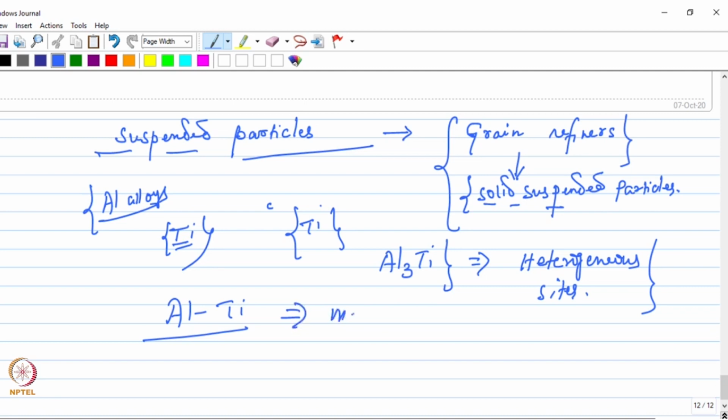because you cannot add titanium just like that into the liquid aluminium. Rather, you already have this titanium in aluminium in the form of these master alloys, and then you can take a very small amount of this, a minor amount of this master alloy having a certain percentage of titanium is enough as a grain refiner.